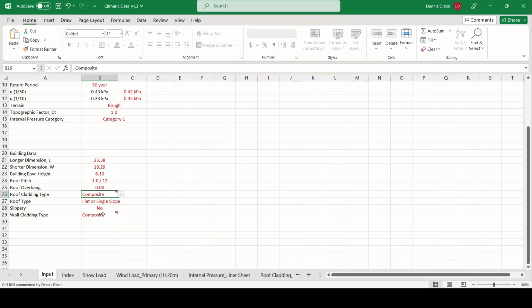And then from my calculation, I will usually add 10 to 15% extra to the reaction from my analysis, and I will use that as the load for the design of the foundation, because sometimes the general contractor is not selected yet, or it's already selected, but the building supply for this pre-engineered building is still under tender.